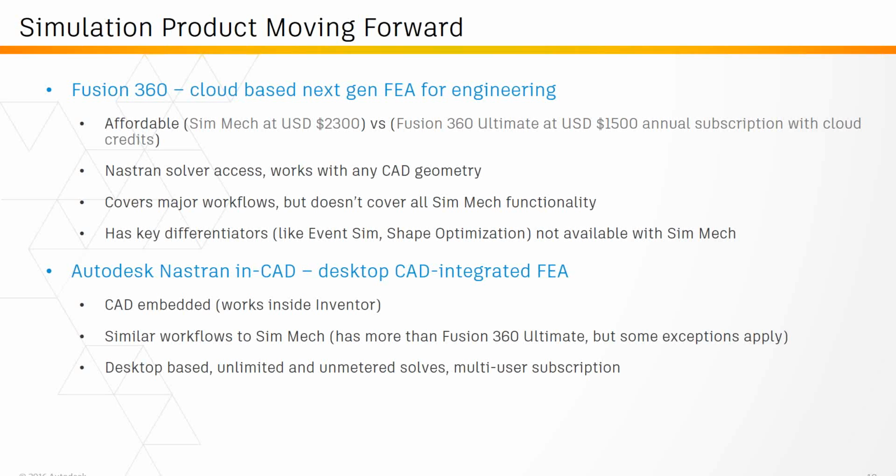And versus simulation mechanical, and we'll get into this further in the deep dive, you do have a couple of differentiators. So we have the event simulation, and when I say event simulation, it even goes beyond the MES. We're talking actual post-failure type of behavior, so drop tests, beyond drop tests, breaking apart, maybe like a fracturing of, sort of like a redundant design type thing where you might break a blade away and you want to see if the containment ring is going to catch it. That sort of approach. So more of a post-failure capability as far as the event simulation.